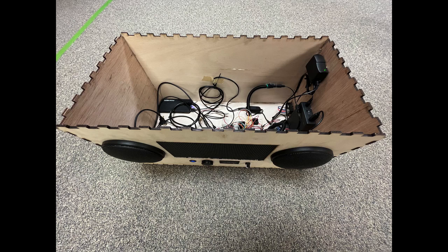Our system is enabled by a 12-volt and 5-volt dual voltage system. This dual voltage system is supplied through a single voltage source, which allows us to avoid any potential grounding issues. Our 12-volt source primarily powers a Class D audio amplifier supplied by Adafruit, which powers our 30-watt speakers which produce our sound. In parallel with this 12-volt source, we also have a voltage detector, which essentially allows us to monitor our battery capacity at all times.